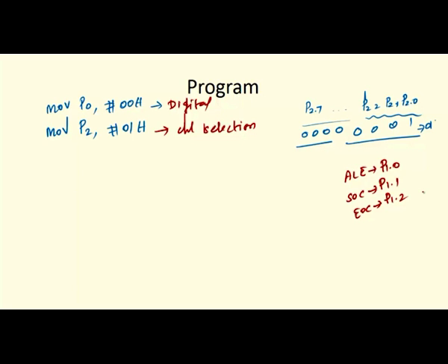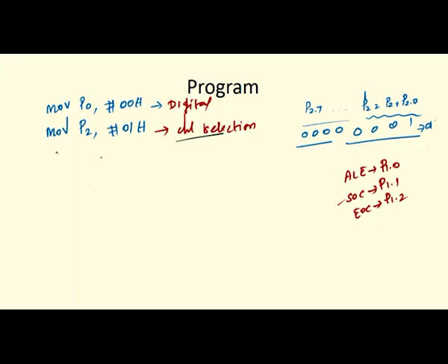Okay. So, you keep in mind to write the program. We have initialized the output and the channel selection. Now, we have to activate the ALE signal, by giving the set bit, which is port 1.0, right. I have to maintain this for a few seconds, so I will insert a no operation and then a clear signal for P 1.0. This is for ALE.